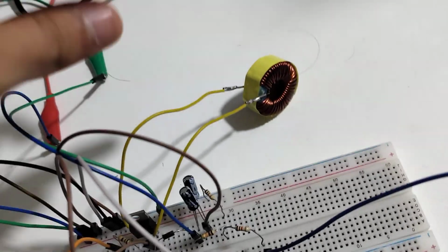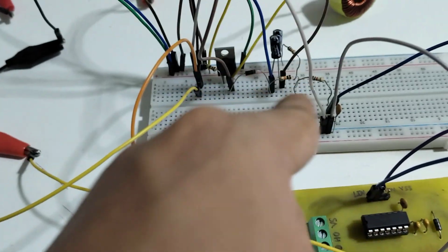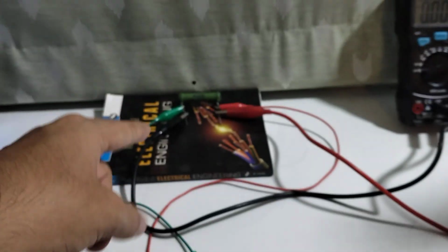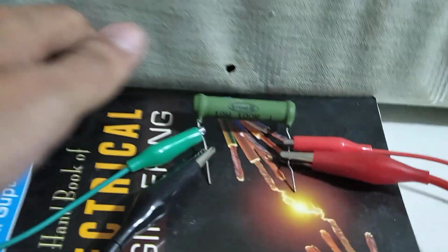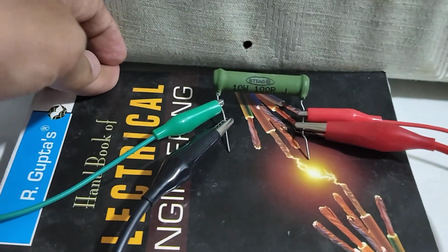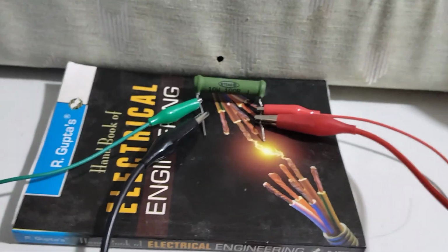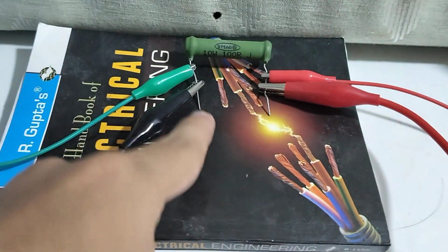And our inductor here, 330 microhenry, toroidal type, and capacitors 20 microfarad and 10 microfarad in parallel. And the load here, since of course there's a breadboard, you can't put a power resistor inside this. It will probably destroy the contacts or not even go in. So we have this here, 100 ohm. This should draw a decent amount of power at 24 and 30 volts. So it's 10 watt rated. Don't use those small puny ones, they'll just burn up immediately. So through the crocodile cable, it's connected across the load.